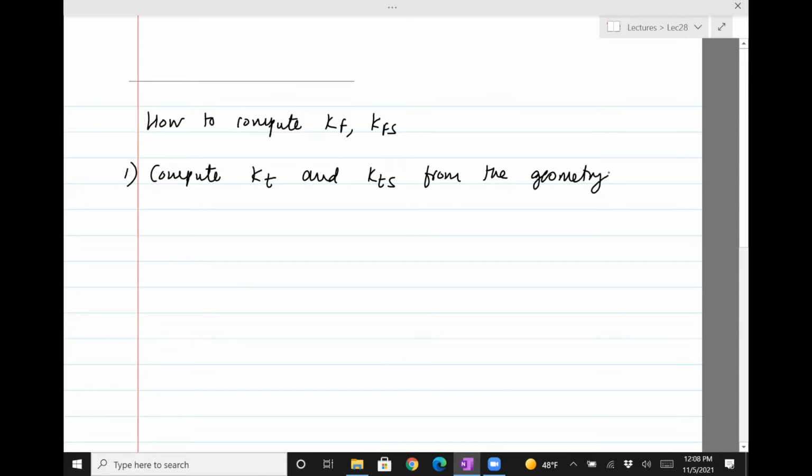Okay, so this is something we've covered in chapter 5, section on stress concentration. So once you define the geometry, you can refer to the right table in the appendix, and that gives you the stress concentration factor, KT, based just purely on the geometry.